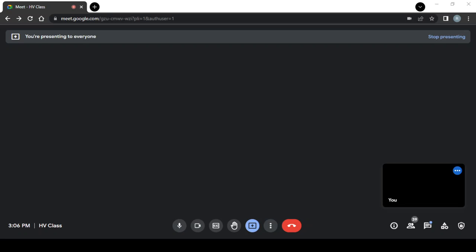Okay, next is the generating voltmeter. Generating voltmeter, this is not very popular. Normally we'll just use a voltage divider. We have a variable capacitor, an electrostatic voltage generator, which generates current. This one will generate current proportionate to the applied external voltage. It means that if we apply 10 kV, this one will generate more current. We apply more voltage, there will be more current.